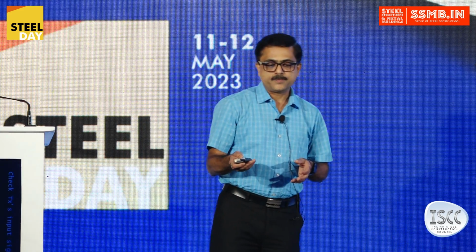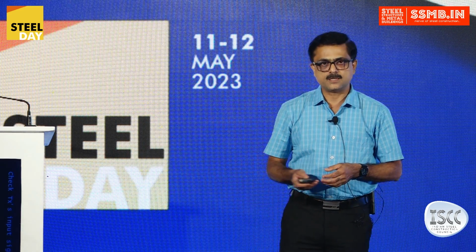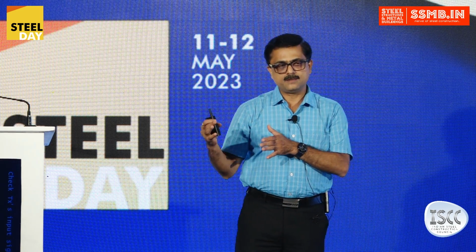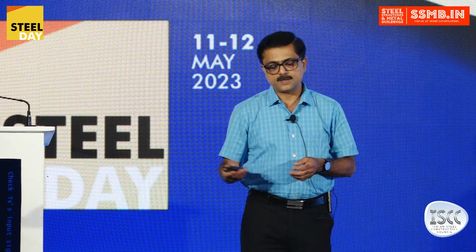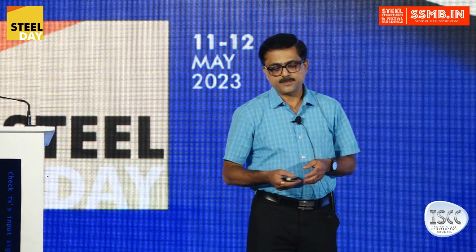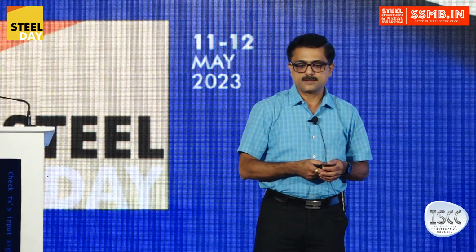The I section has a natural property to give resistance by using its torsional stiffness. However, that stiffness is very low, and we cannot rely on it each time. So what are the factors that affect lateral torsional buckling? It's the cross-sectional properties, then the material properties, then the length of the beam, then the support conditions the beam is subjected to, then the initial geometric imperfections.